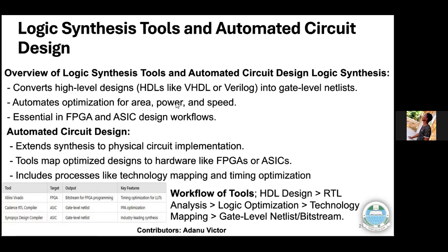Here you are trying to map and optimize the logical representation of the circuits. You are going to be introducing some hardware components like your flip-flops and the likes of it. The tools that you could use in this stage would be Synopsys for ASIC or Vivado for FPGAs.